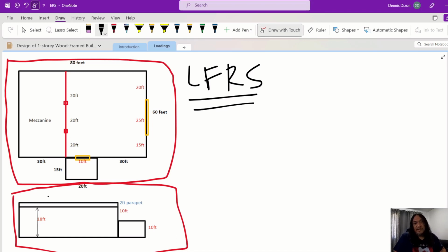For wood frame, you can also use a masonry shaft or a concrete shaft for your shear wall, but it's common to use a wood shear wall instead of a single elevator shaft in the middle of your structure.